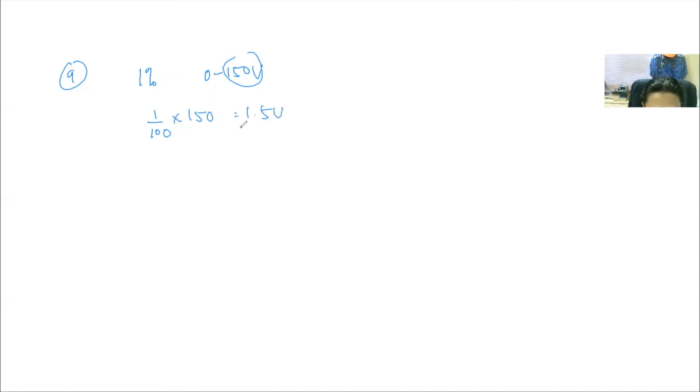That is the plus minus tolerance. But the value by the instrument is 83 volts. So from this, 1.5 divided by 83 multiplied by 100, you can get 1.81%. So this is what we call the limiting error for the 83 volt measurement.